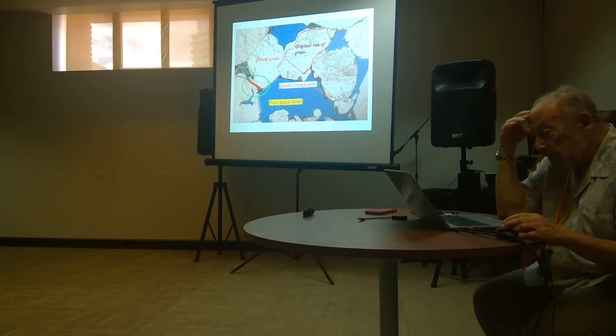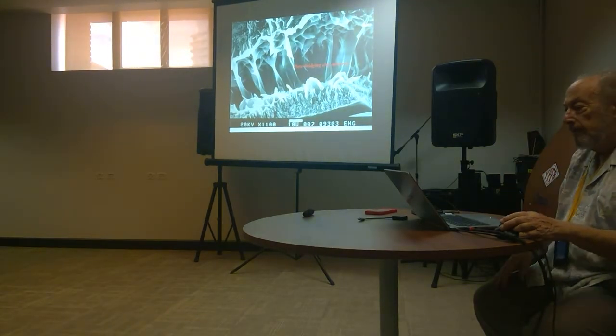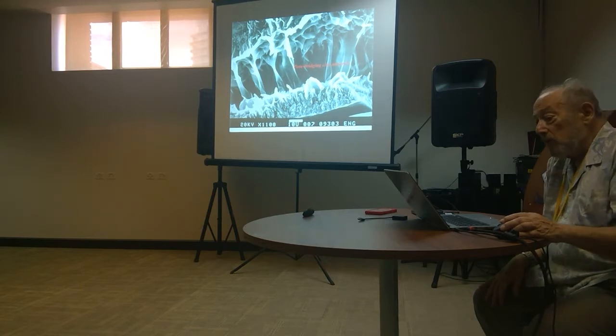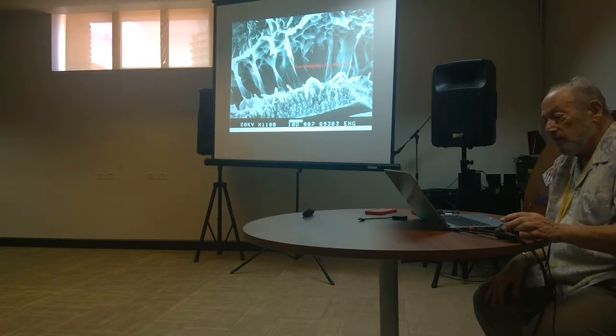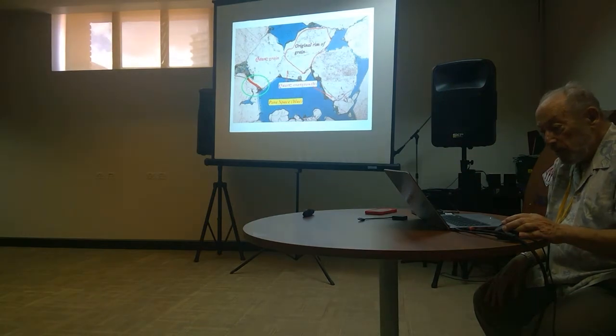So we're going to zoom down now and see what's connecting these two grains together. And this is what we find. Here's the remnant of the separation of the two grains. In other words, there is a little bit of porosity here, a little bit of porosity right down in there.